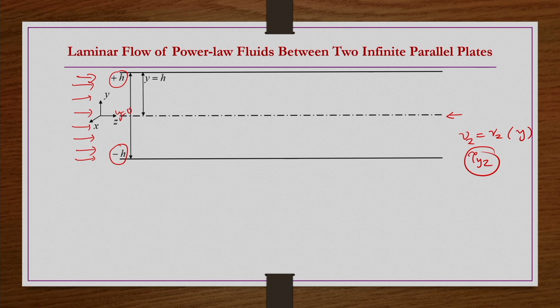Rest all others we are not going to have, since the material is a time independent non-Newtonian fluid and there is no elasticity. So, normal stresses are altogether not existing, and the other components like tau xz, tau zx etc. are negligible. So, we are going to have only tau yz.